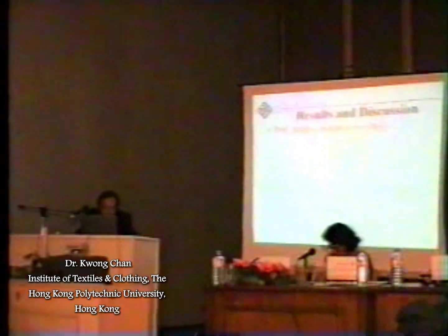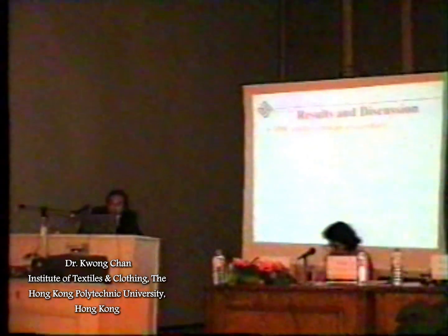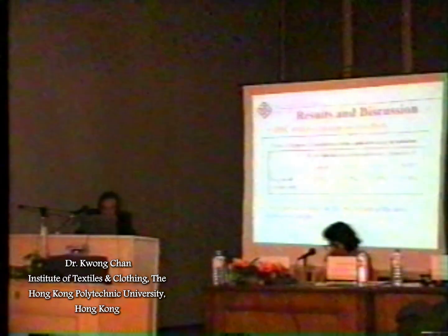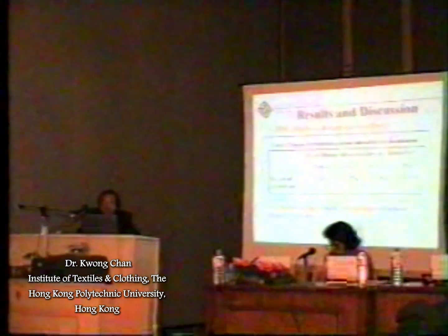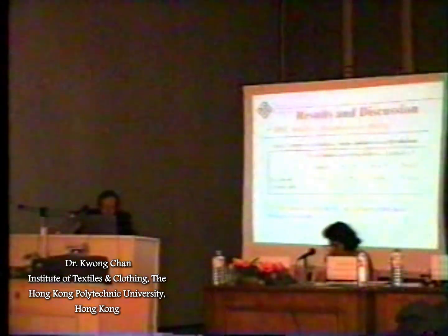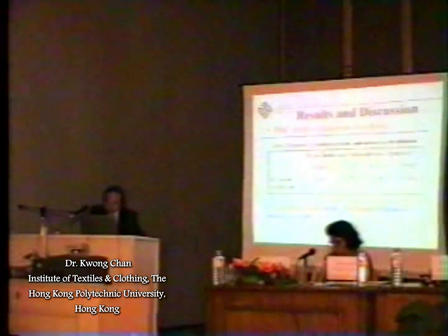The DSC study shows the changes in crystallinity. It is found that there is no significant change in the crystallinity of the laser irradiated samples. That means the laser treatment is just a surface treatment which does not affect the fiber bulk properties.